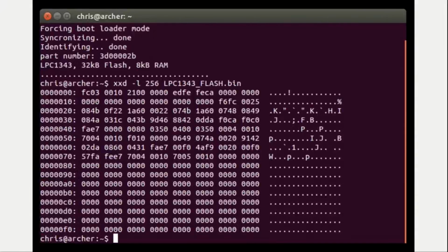We've been able to identify the locations in the boot ROM startup where it's checking the code read protection values, where it's checking if it's allowed to access the bootloader. We perform a glitch at that location. It's able to corrupt the code flow, but the chip still operates other than a few corrupted instructions. So we've entered the bootloader. Once we've entered the bootloader, we can drop back to any of the LPC programming tools, and it's able to just read the chip normally as if it was an entirely unlocked chip.